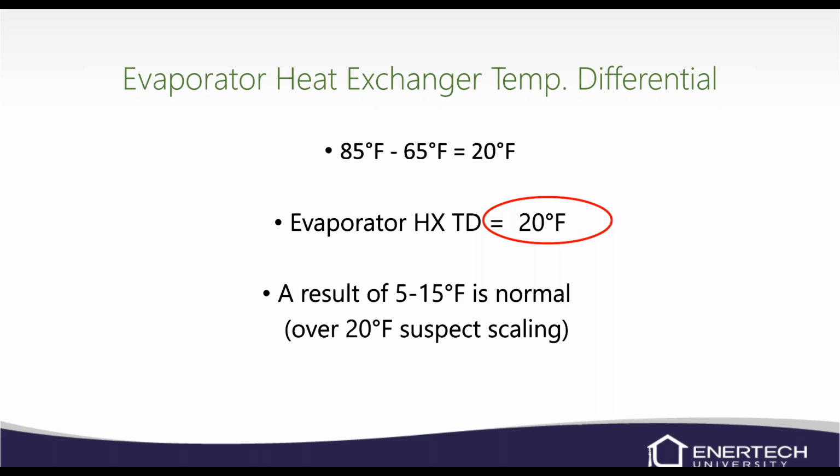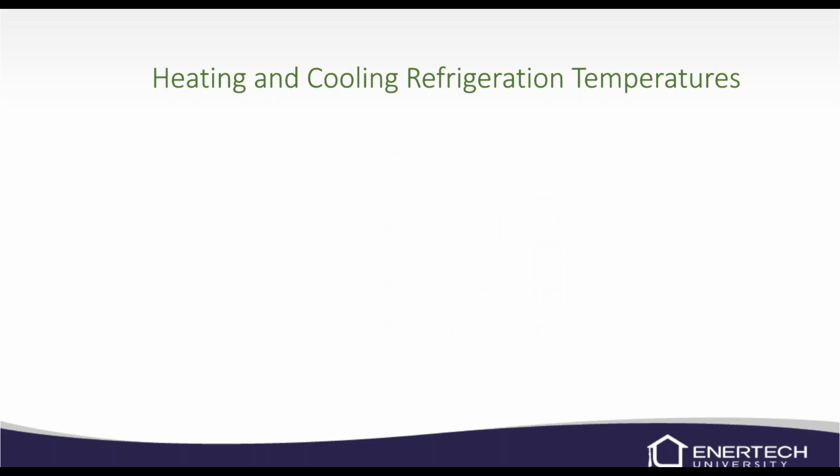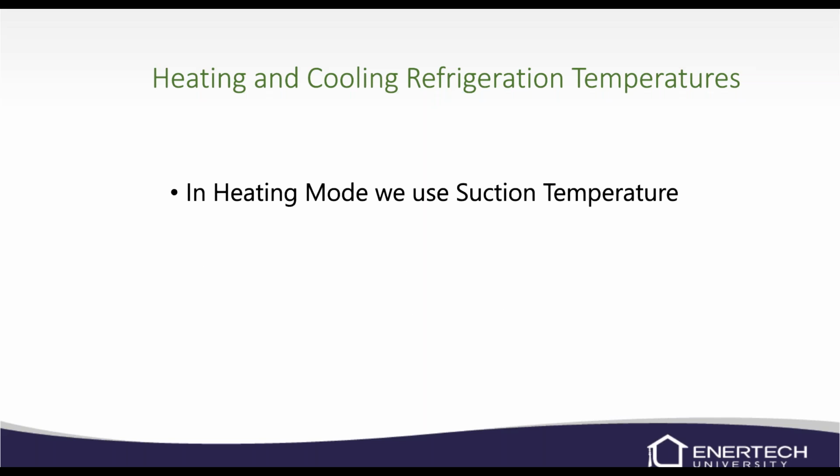You can use that, and you'll basically just flush that through your boiler drain valves that you have on your open loop system and circulate fluid through there and clean that heat exchanger out. Then after you've got it clean, you can actually redo the calculation and make sure that number has dropped within your normal range. So one of probably the biggest maintenance needs on an open loop is using this calculation and keeping that open loop system clean.